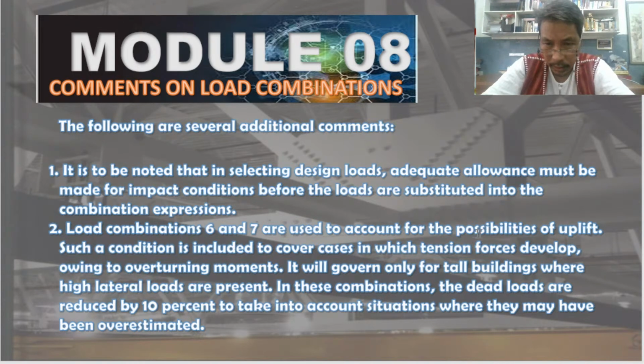Let's continue with the possibility of uplift. Such a condition is included to cover cases in which tension forces develop owing to overturning moments. Because when we have overturning moment, one side is compression, the other side is tension. It will govern only for tall buildings, where high lateral loads are present. In these combinations, the dead loads are reduced by 10% to take into account situations where they may have been overestimated.